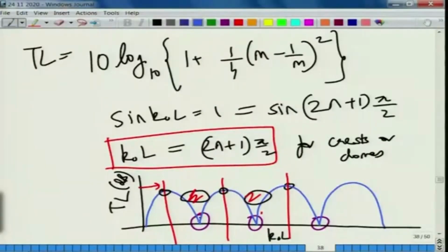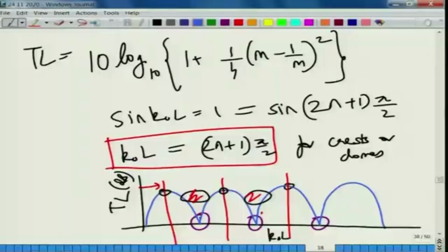So by ensuring a broadband performance of a muffler, we really are ensuring that there is no trough like what we saw in the graph presented here. Of course, a simple expansion chamber is too simple to be used, but probably the most well studied element and probably the first element that we have studied in this course and all the courses in noise control engineering.